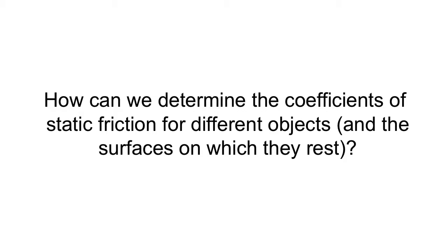So if you think about what would happen, I would increase this angle. So I'm tilting the ramp more and more and more. And at the maximum angle, just before it started slipping, I know that the system's in equilibrium, and I can extract this value of mu s that keeps it there, right? So what I have to imagine is that I increase to some maximum angle, and right before it starts slipping, it's still held in place.